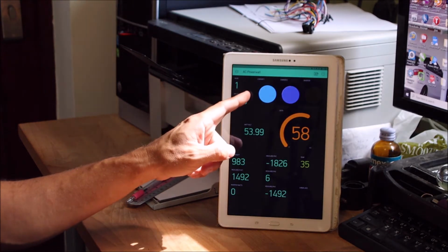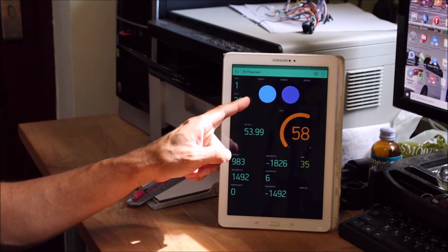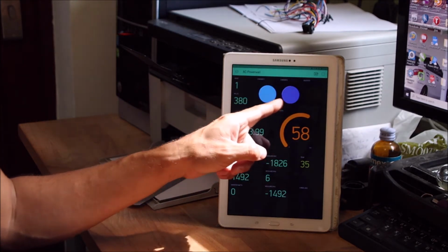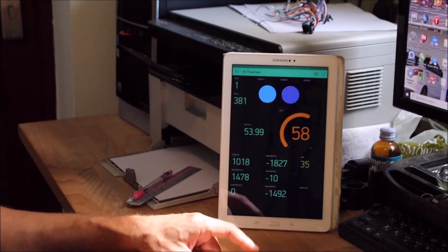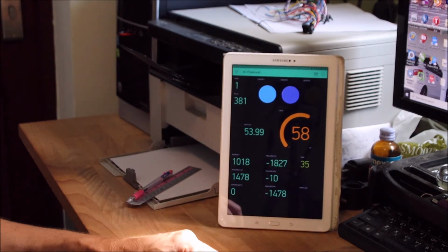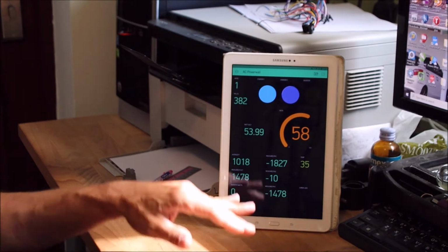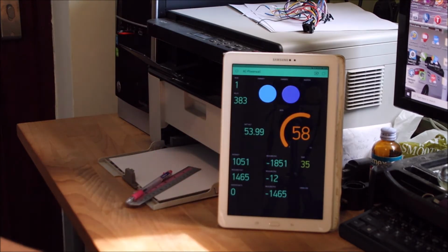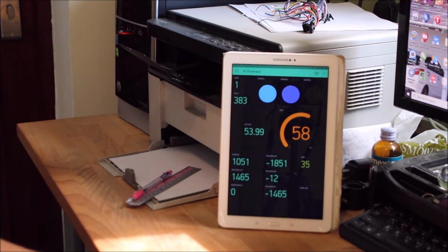So what do we have here? We have now 4 LED indicators. So this is showing the chargers. Now both are activated, the inverter is off, and then here's a fourth one which is called the charger lock. So when the Powerwall is basically reaching near the full state of charge, then one of the chargers will be locked, and only one will then finish the job.